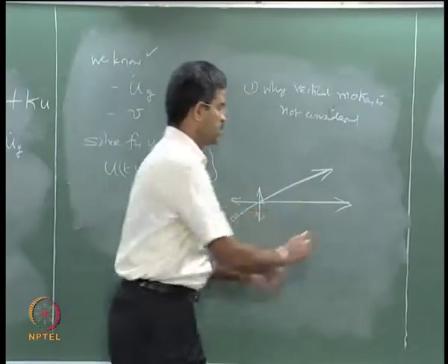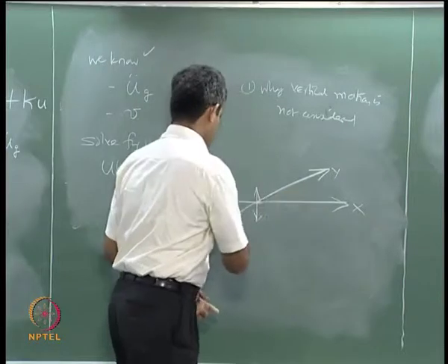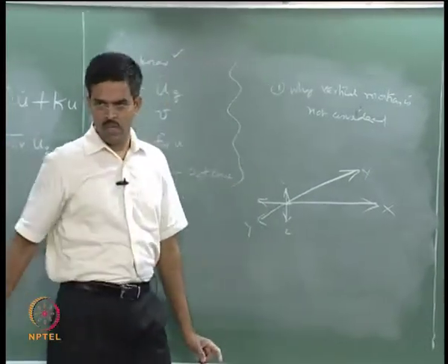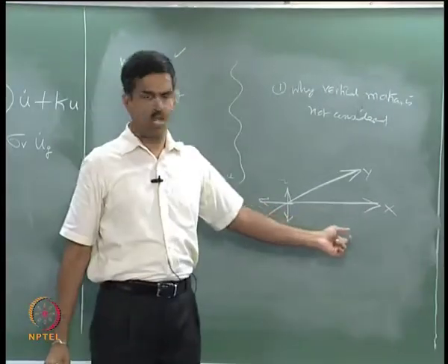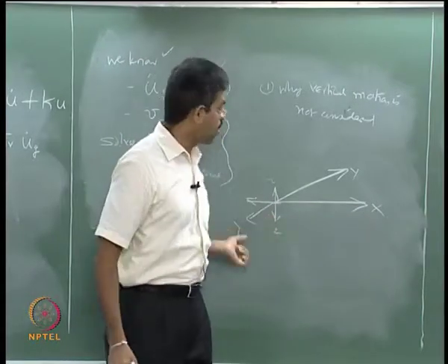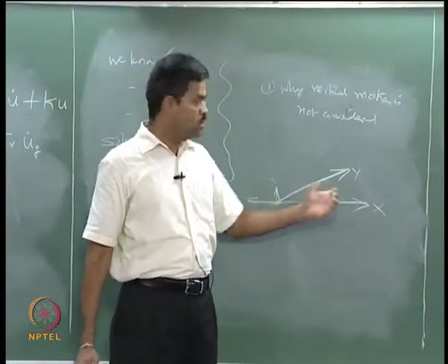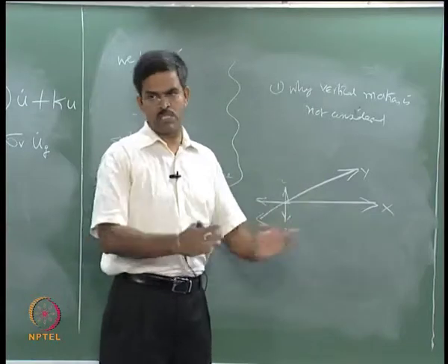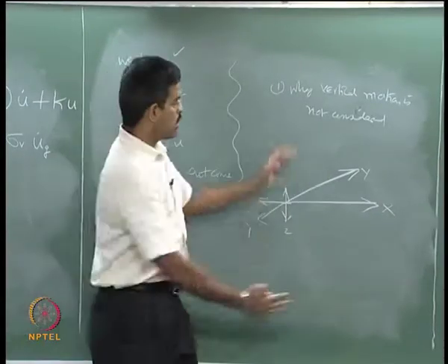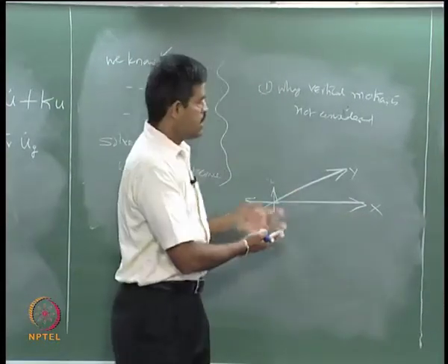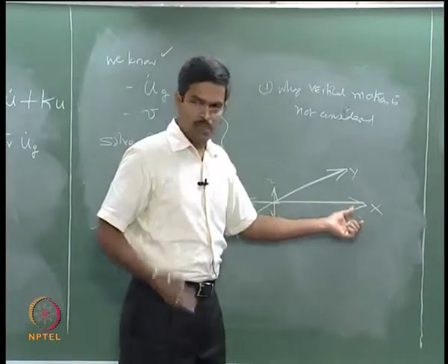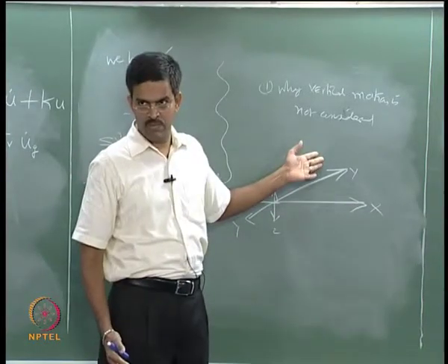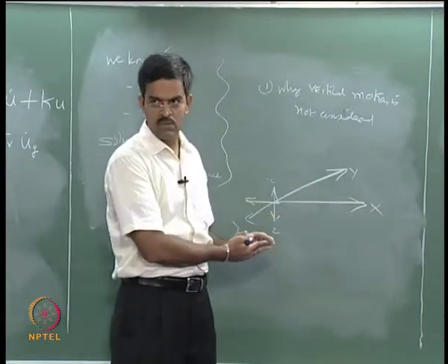Okay, along x, along y and along z. When I am talking about unidirectional force, I will take either along x or along y. I can do analysis in both forms and see which is the maximum response. If you want to combine these two, then IS 1893 says take x plus 30% of y only. Okay, you can combine this also, right.